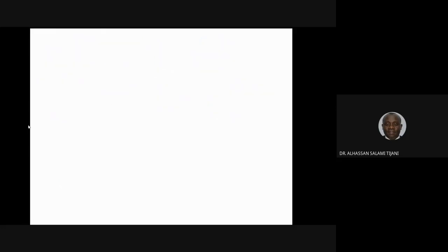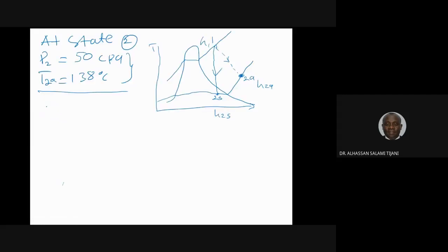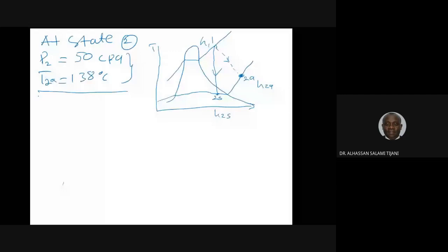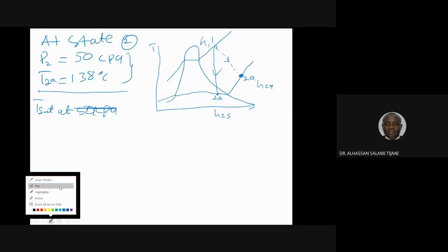Now from this particular state, we can determine whether this state is in the superheated or saturated liquid-vapor mixture region by finding T saturation at 50 kilopascal.